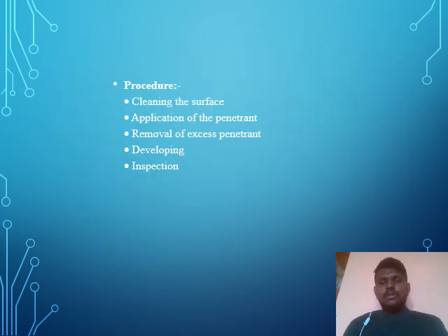The procedure of the liquid penetrant test is as follows. We have to clean the surface, then apply the penetrant, and then remove the excess penetrant which we have applied. Then we have to inspect it.